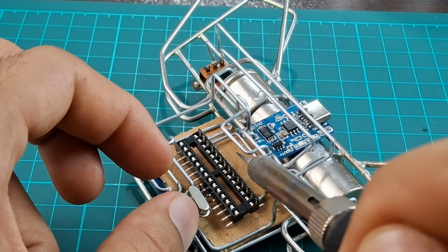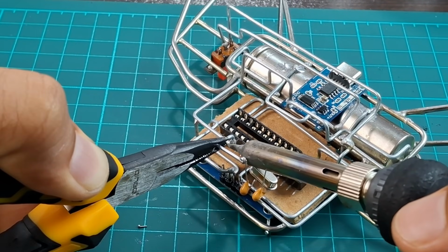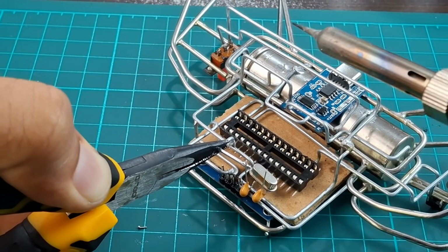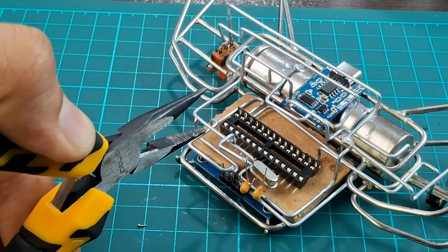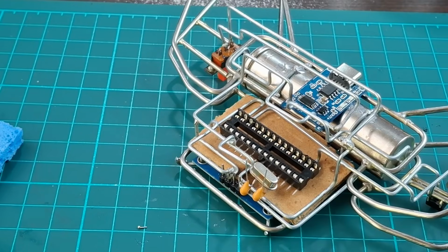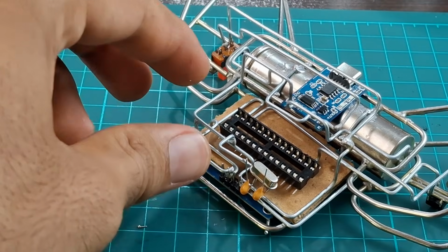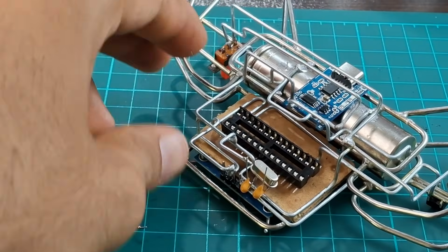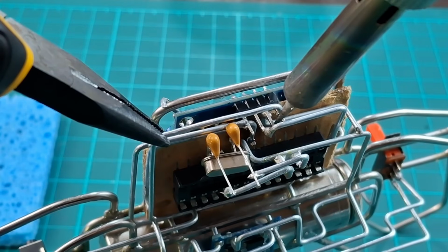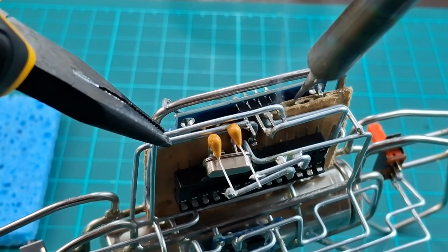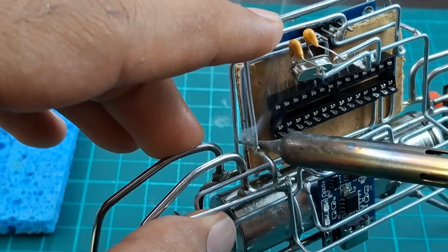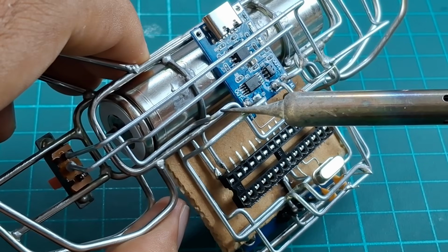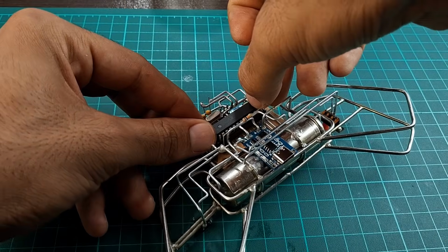And look at this. I'm soldering one connection to the ground with the tip of the iron, while soldering the other end using the body of the iron. This is a very rare soldering technique that lets you solder 2 points at the same time. And by the way, this is the exact same technique that burnt my display earlier. Then I soldered the VCC connection, but I made a small mistake here that was going to cause a huge problem later. Finally, I added a pull-down resistor for the push button, and we are done soldering.